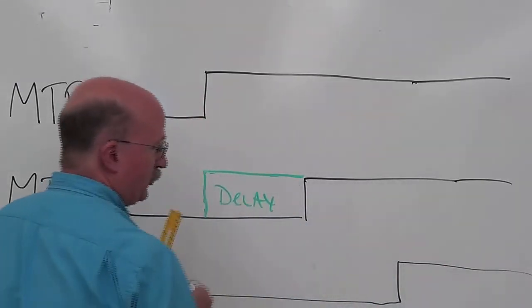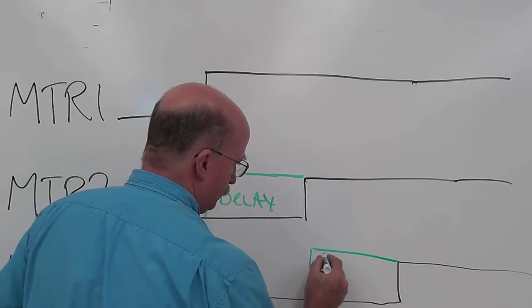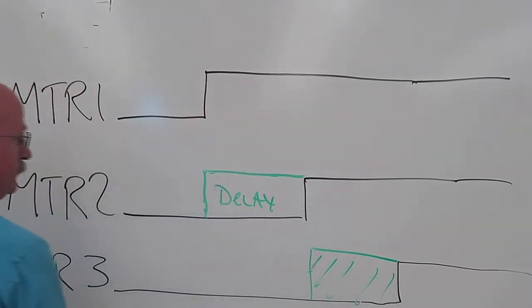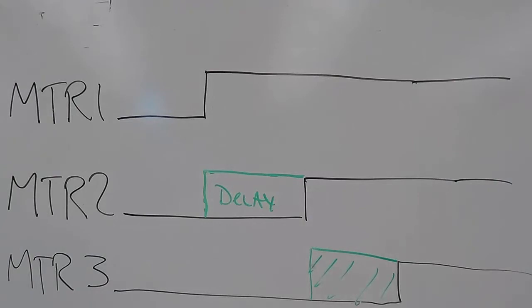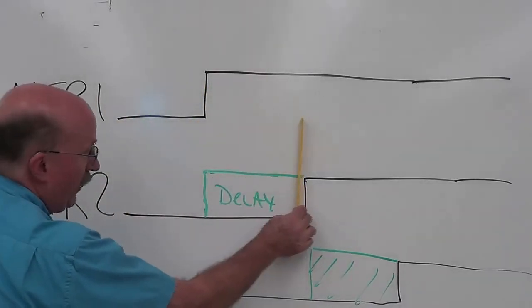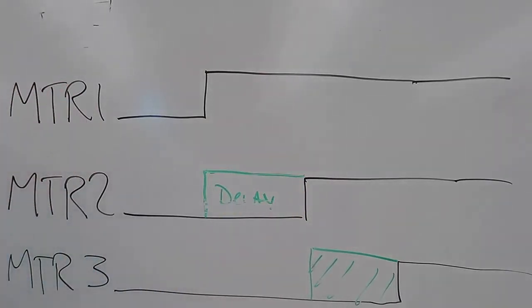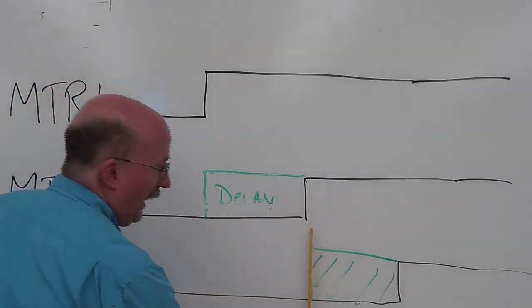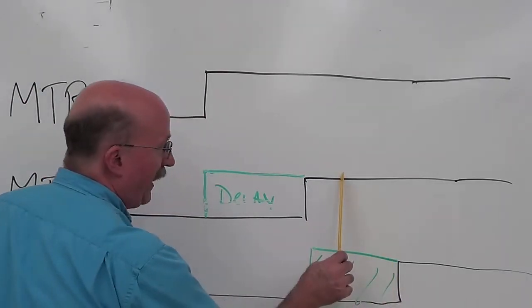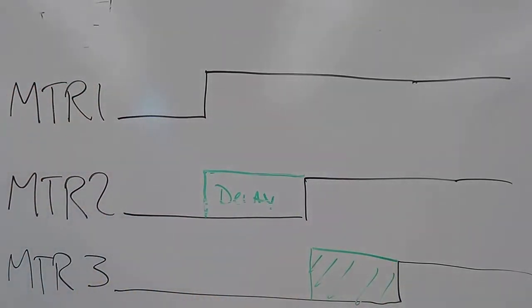And you've got the delay associated with that. So in your specification, when any motor is starting, if motor 1 is stopped anywhere during this delay period before motor 2 turns on, it has to stop immediately. Right? So motor 2 is on, and anywhere in this delay period, if I stop motor 2, it stops immediately, and then the next one starts the countdown delay for motor 1, and then motor 1 will shut off after that.